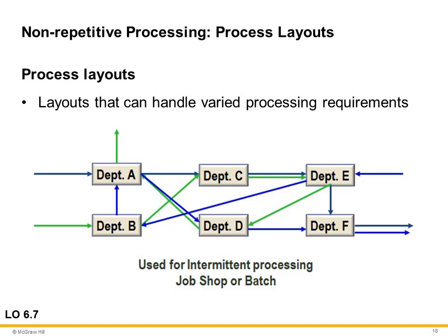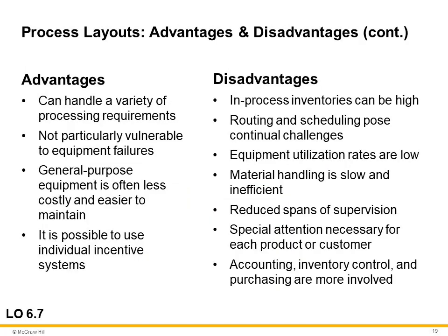Similar to product layout, there are advantages and disadvantages of employing process layout. An advantage of the process layout is that each station or department can address a variety of required work or processes. And as a disadvantage, your in-process inventory is higher than with other types of layout.